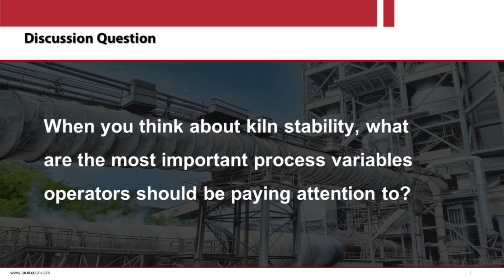The draft pressure, of course, is mostly the most used variable to judge the overall system balance, a bit everywhere: at the preheater, at the kiln inlet, and at the TAD.